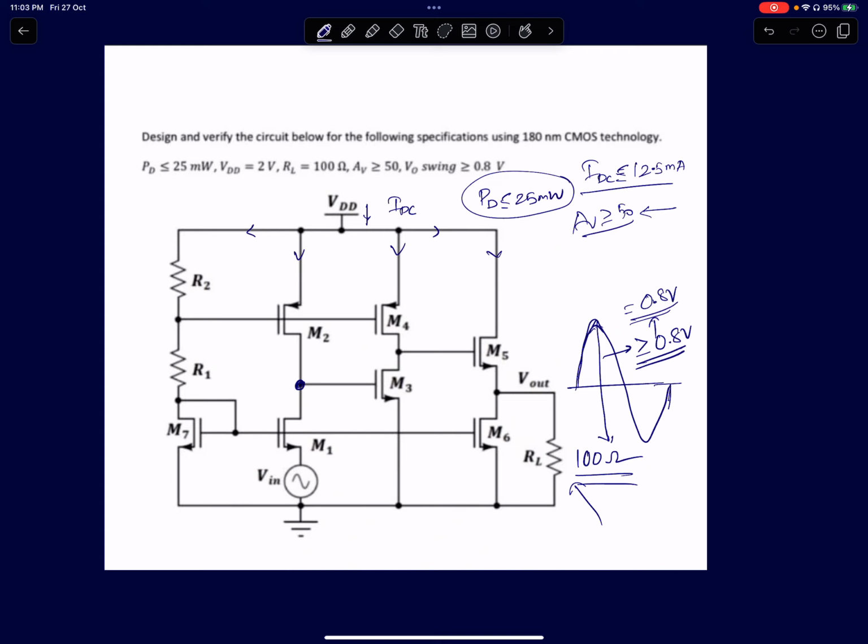Just see if it has some simplicity or simple repeating patterns in it, then you can analyze it much easier. The first circuit, if you look at the first transistor M1, input is at the source, output is at the drain. So it's a common gate amplifier. The upper transistor M2 is just a biasing transistor.